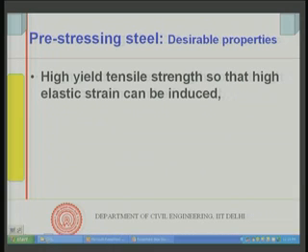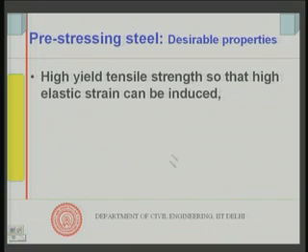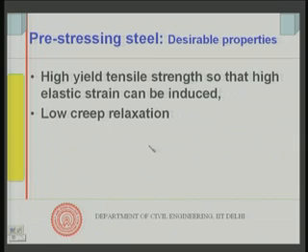Pre-stressing means I actually pull the steel, and it should have high yield and tensile strength, so that high elastic strain can be induced. Now, we mentioned creep and relaxation in the case of concrete. Under load, if it is deforming, so I have pulled it up, and if there is creep and it deforms more, there will be some amount of relaxation.